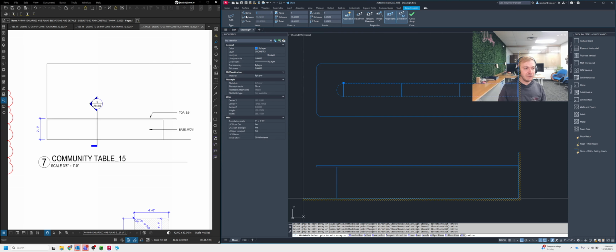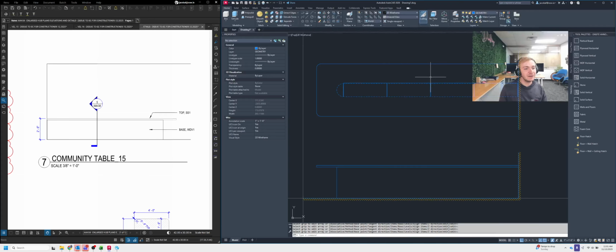an inch. I want to get that down a little bit further, so we're going to go 5 reveals. And we're going to go 1, 2, 3, 4, 5 reveals, which means 4 panels. And that brings us down to 38 and some change, which is a lot more manageable than doing a 50-something inch panel. So we're going to hit close array.